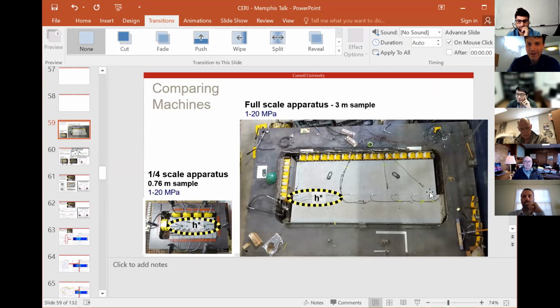So I wanted to do a bunch of experiments on this one before damaging the samples, because it's the same rock we've been using for about four or five years now, before going up to 20 MPa. But before too long, we will take it up to a higher stress, though we will eventually be limited by the capacity of the machine, which is around 20, 24 MPa, and then the fact that the granite's just going to start to crumble.